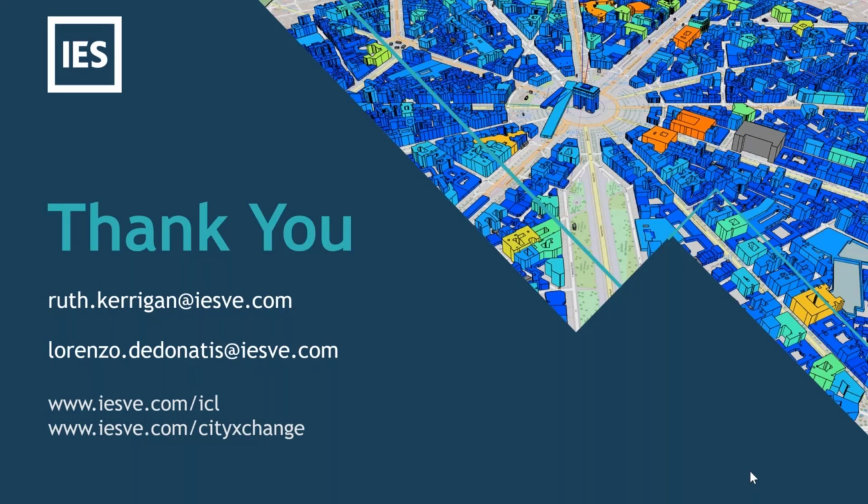Konstantin is asking how you calculate heat losses and U values through the ground floor, because heat losses depend on the type of ground and the U value is affected by corners and the center of the floor. That's a good point. The U value I showed was the U value of the floor itself. The model will also consider thermal bridges, for example at the corner between the ground floor and the internal wall, or the ground floor and the other wall. The software takes the thermal bridge into account, but the U values I showed were only for the package of the ground floor.